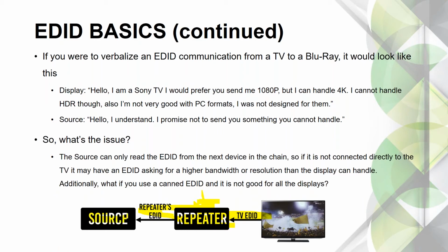You get audio dropouts. You get two-channel when you're supposed to get multi-channel. You get the wrong resolutions. There's a lot of issues, or even no picture. So we need to be able to manage this situation. When we're doing a multi-zone dwelling, and we have lots of inputs and lots of outputs, this EDID management becomes critical.